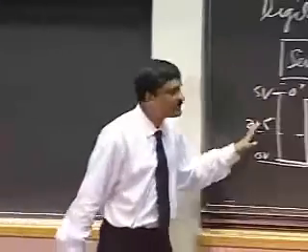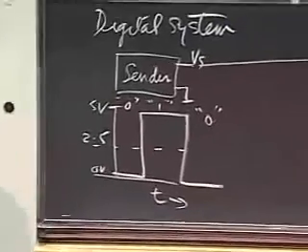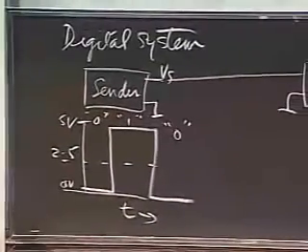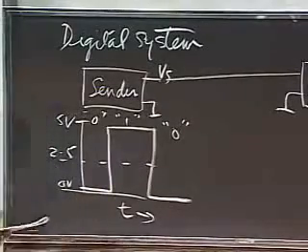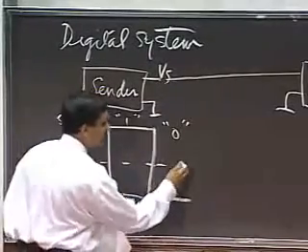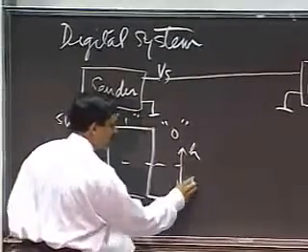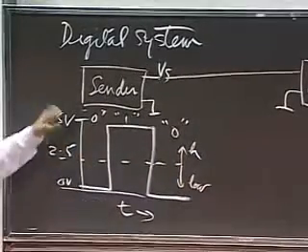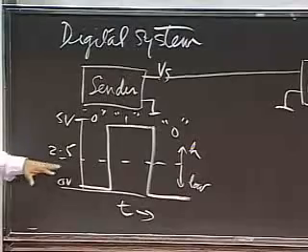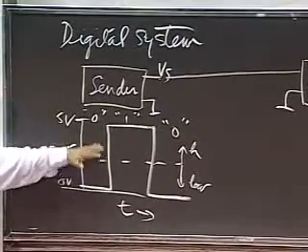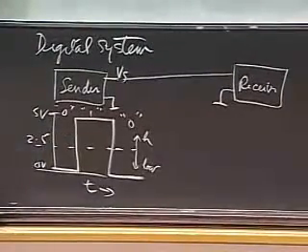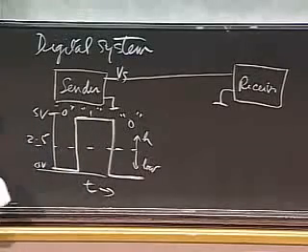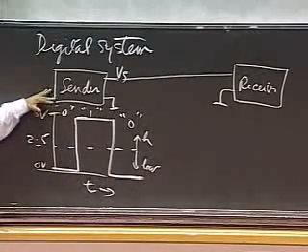This simplistic scheme will not work in many situations, but go along with this for a few seconds. So I send the signal sequence 0, 1, 0 out here, and notice that there is a high and a low. And the agreement the sender and the receiver have is that, look, if you see a value that's higher than 2.5 volts, that's a high. If you see a value below 2.5 volts on the wire, that's a low. And I'm going to send a 0 volt or a 5 volts from here.